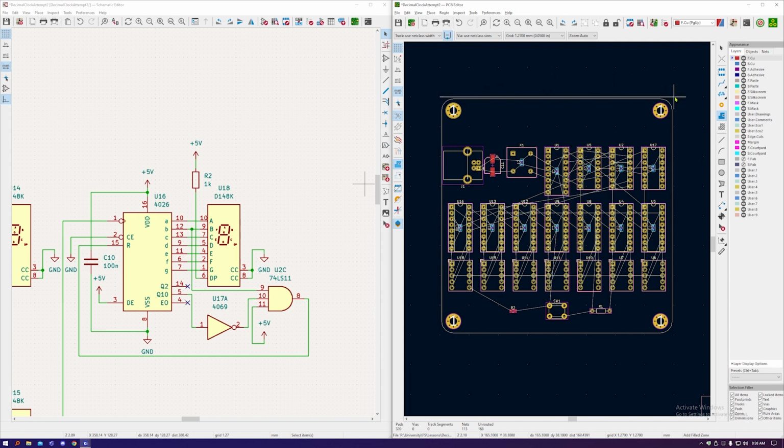If you're on the Formula Student team, the convention that I want to try and stick to is ground on the front, power on the back, or ground on both sides in some cases. This board is nice in that everything's either ground or 5 volts, but sometimes you'll have multiple supplies. I recently made a board with 12 volt, 5 volt, 3.3 volt and 1.8 volt.